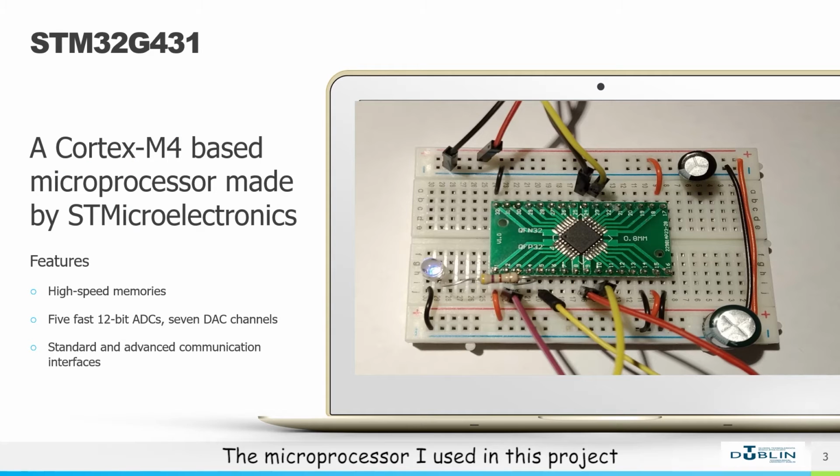The microprocessor I used in this project is called STM32G431. It is a Cortex-M4 based microprocessor made by STMicroelectronics and equipped with high-speed memories, 6 DAC and ADC channels, and standard communication interfaces.